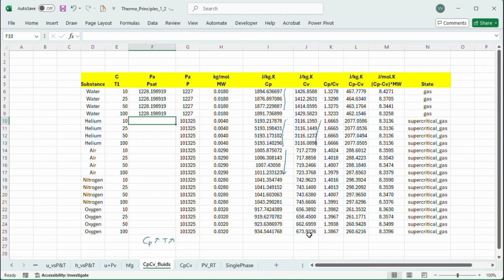So when you're trying to calculate the energy needed to raise temperature from, let's say, 10 degrees to 500 degrees, a lot of times it's okay to use a constant CP for the process, even though the CP is changing the entire time. Ideally, though, you should take an average CP of that process, like the initial and final, and then take an average CP. And it's even better if you could do an overall integral average for the whole process.